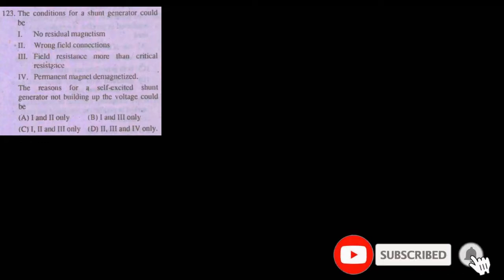Okay, next MCQ: the condition for a shunt generator could be no residual magnetism, wrong field connections, field resistance more than critical resistance, permanent magnet demagnetized. So the reason for a self-excited shunt generator not building up the voltage could be, so no residual magnetism, then there will be no building up of voltage.